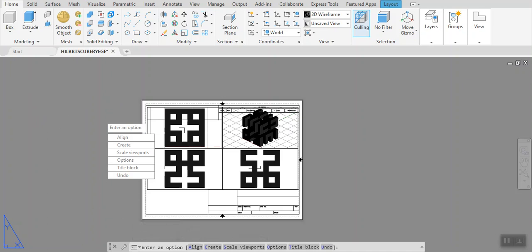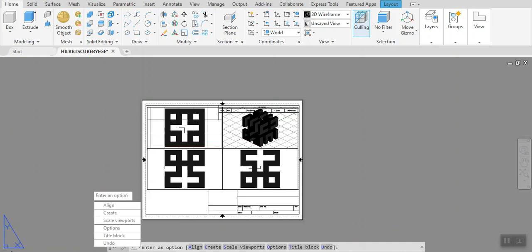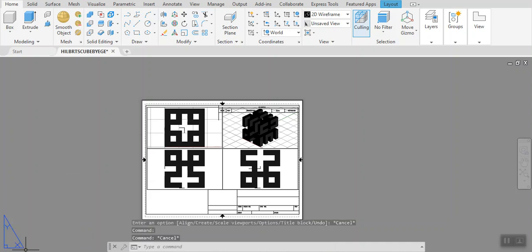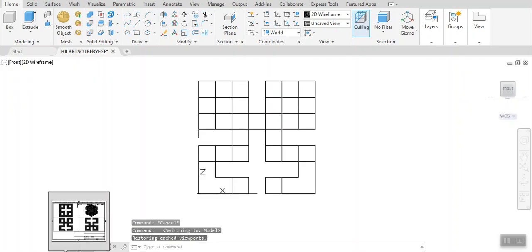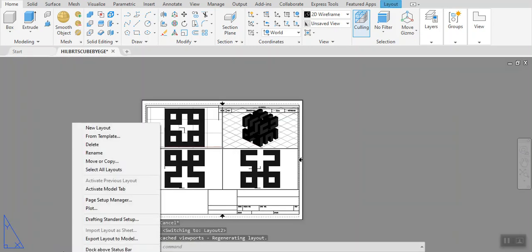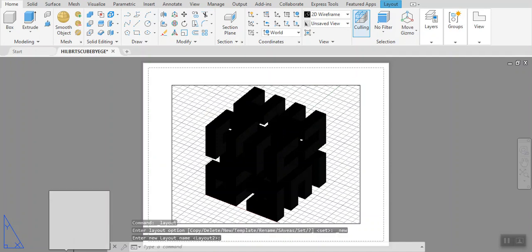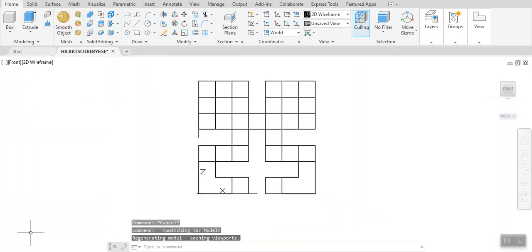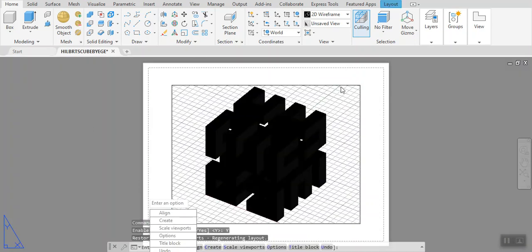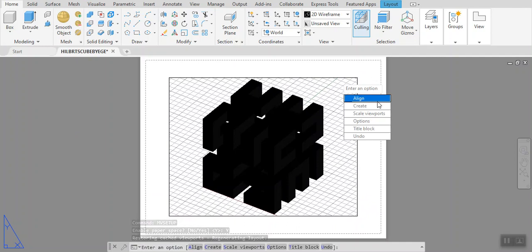What I'm going to do, I'm going to take you back. Go back to model space, escape, and erase the layout template. And go to model space and go with the MV setup command, so that we can start all over. Enable paper space, yes. And now we have the paper space created in front of us.